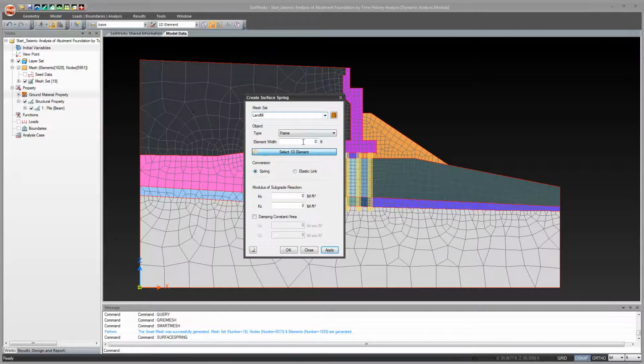And then the element width, let's make it 3.281, so roughly 1 meter. And then element boundary curve, and then damping constant. Here you just have to define your damping constant. I don't have the equation offhand, but just using the material parameters that are available to you now, or the ones that came with the Mohr-Coulomb model, Poisson's ratio, modulus of elasticity, and a couple of other ones, you'd be able to define your damping constant for each of these layers here.